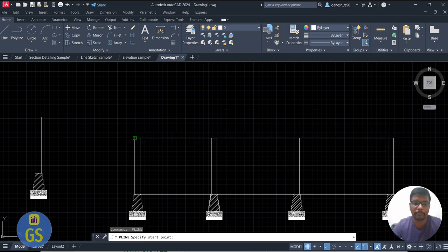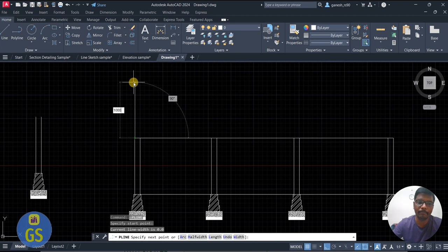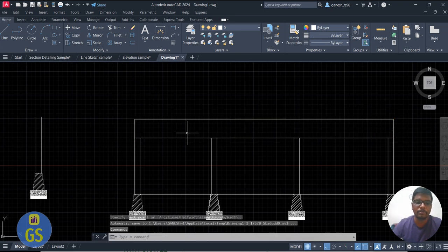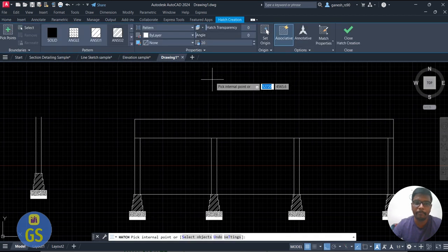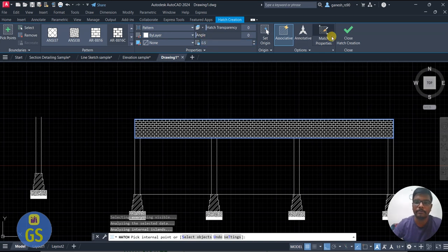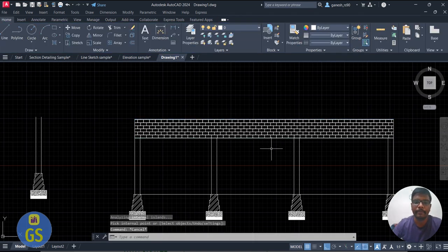Now you can make the parapet 1 meter, that is 1000. Then go ahead here, right? Now you can show some brick work on the top. You can have some brick walls. Go for brick walls. You can increase it to 50, or you can go for 12, 10. Let's go for 0.5, right? This might be better, or that's 0.75, much better. Okay, so now you can see the brick wall, that is a partition parapet wall. So we are fixed with the parapet wall.